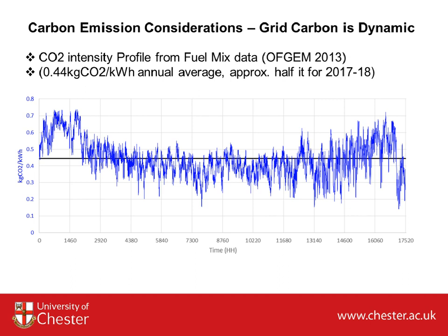As we're going into the summer this year, there will be times where the national grid carbon intensity is almost zero. They will have to keep about 5 gigawatts of combined cycle gas turbines online to be able to reliably regulate 50 hertz frequency. So it will never be zero, but it will get very close. But in the winter, they still need a lot of gas. And that's why I believe distributed CHP is a fantastic resource for the national grid.